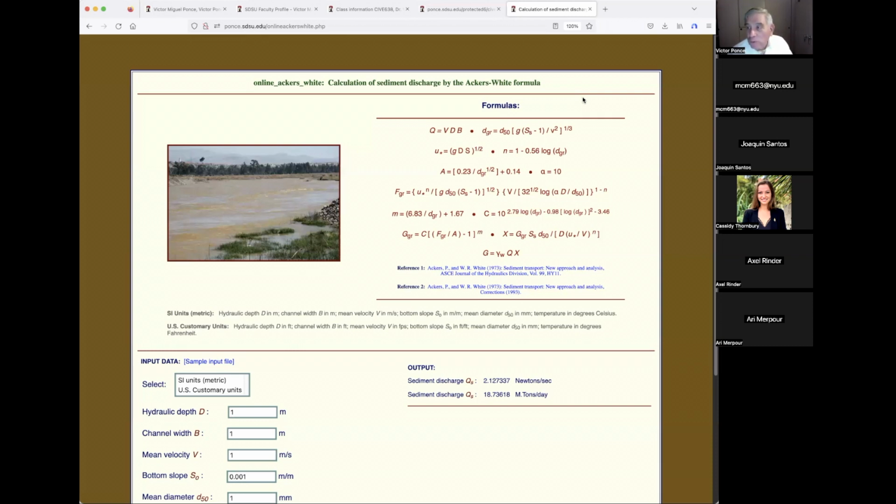It would also do sediment routing, which amounted to HEC6, because HEC6 at the time was the HEC2 with sediment routing. Those programs don't exist anymore, because in 1998, that is 9 years later, they were superseded by HEC-RAS, where RAS stands for River Analysis System, which contains both HEC2 and HEC6 and 2D, and now it has water quality, and they're even getting into 3D. So HEC-RAS is going to be the only model to use, because it's got several branches.